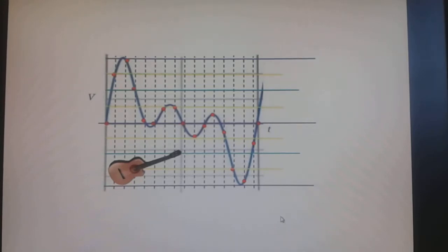The next step is quantization, and the first step in that is to figure out what the maximum and the minimum values are for the waveform. Then we will cut that in half, so here above you will have 1, and this below will be 0. So you have above and below two states, and then we will divide each of these into another two, so we have above and below, above and below.